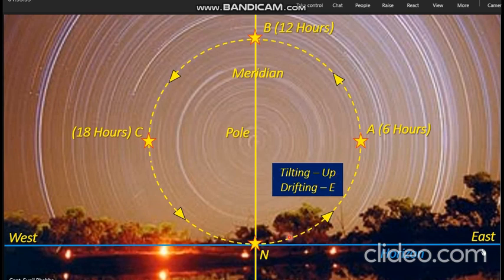The second thing which we note, when the gyrostar is going from November to alpha, it is changing its azimuth in the easterly direction. At point November, the azimuth was 000, and as it moves towards point alpha, the azimuth is changing in the easterly direction. The star is moving towards the easterly direction. Now the azimuth of the gyrostar refers to the drift of the spin axis.